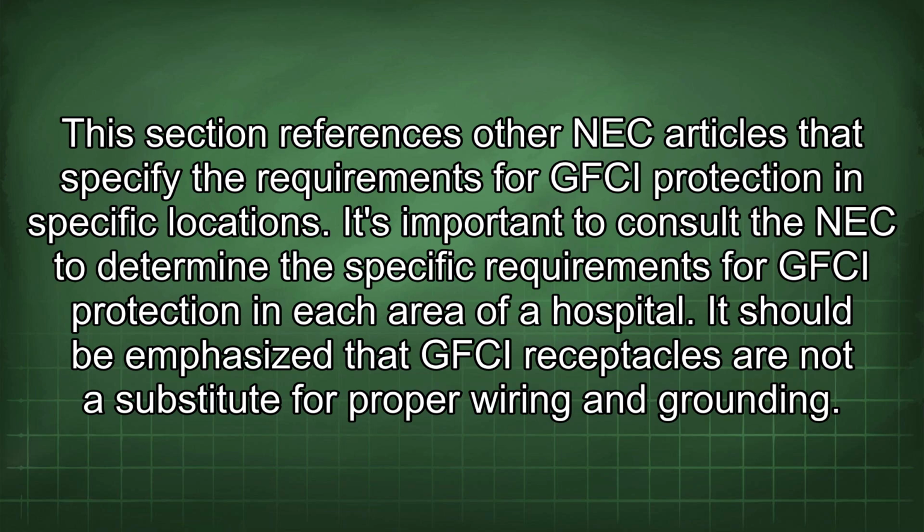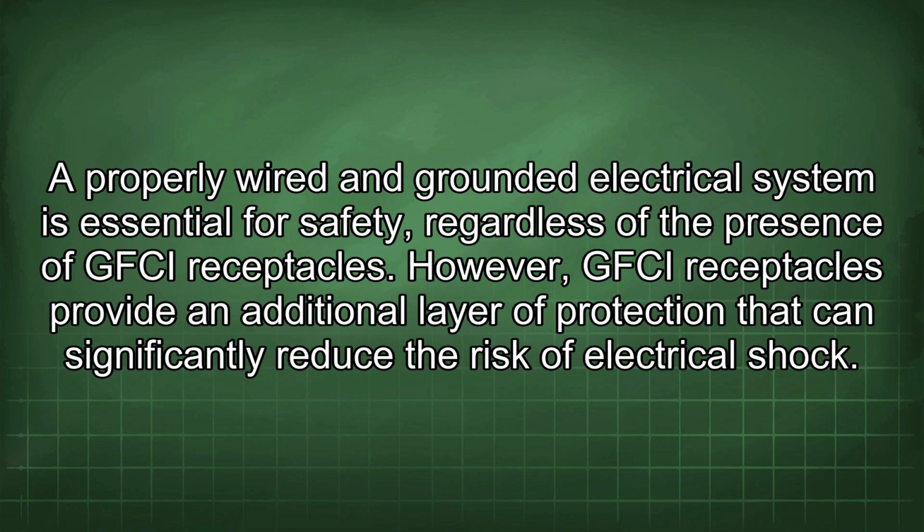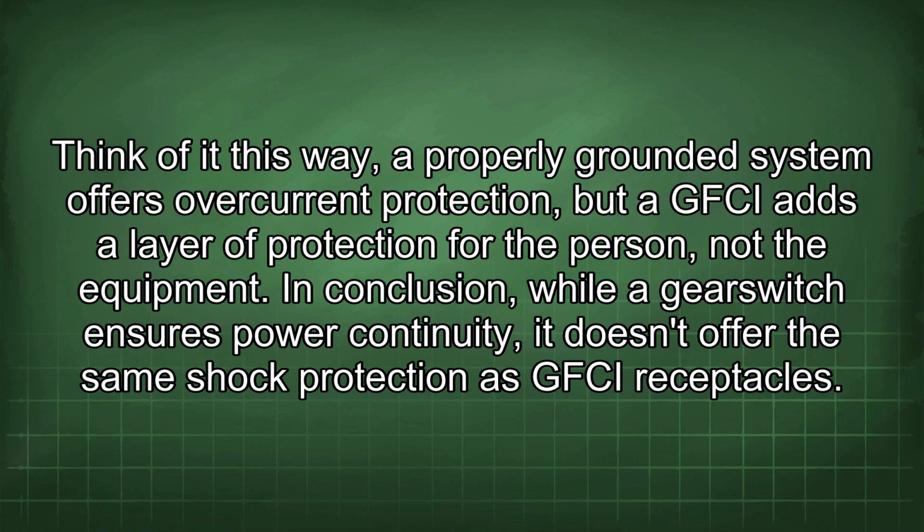It should be emphasized that GFCI receptacles are not a substitute for proper wiring and grounding. A properly wired and grounded electrical system is essential for safety, regardless of the presence of GFCI receptacles. However, GFCI receptacles provide an additional layer of protection that can significantly reduce the risk of electrical shock. Think of it this way: a properly grounded system offers overcurrent protection, but a GFCI adds a layer of protection for the person, not the equipment.